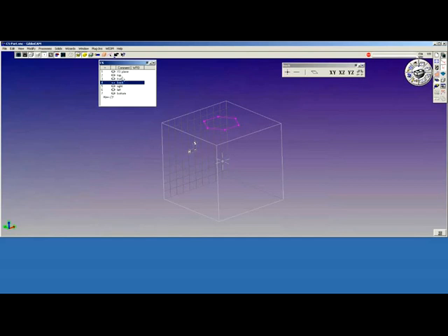Now, if you want to deviate from the default sequence, 54, 55, 56, 57, 58, 59, and so on, in the WFO column, you can type in a number. The number 1 is the first work fixture offset. The number 2 is the second. The number 3 is the third.